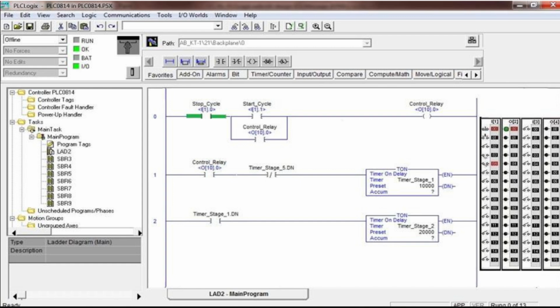These programs are typically written in relay ladder logic, but other standardized languages, such as function block diagrams, structured text, instruction lists, or sequential function charts, can also be used. The software not only allows the user to write the control logic, but also to document the program thoroughly, including labels, comments, and descriptions of the control process. This documentation is essential for troubleshooting, training, and long-term maintenance of the system.